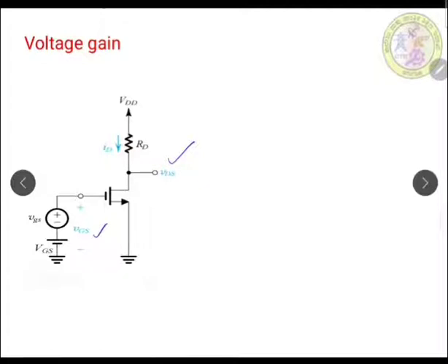As we have been discussing, small v with capital GS, it includes the total voltage, that is, it is the sum of the small signal vgs plus the DC bias capital VGS. So here the instantaneous input is available between the gate and source terminals, and you can consider this small v with capital GS suffix as the input signal.